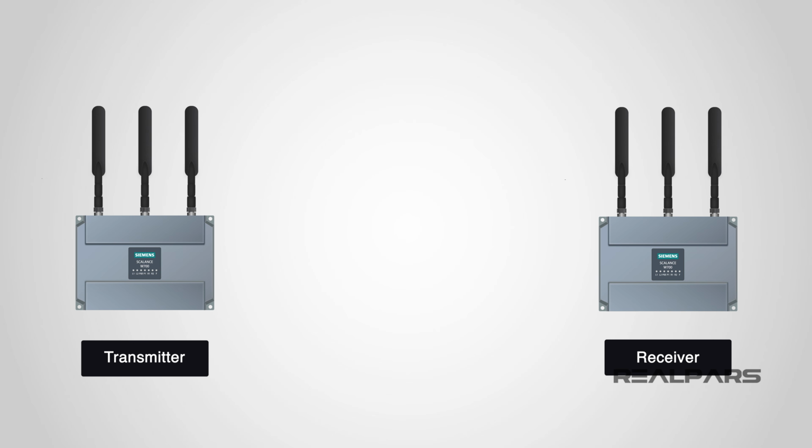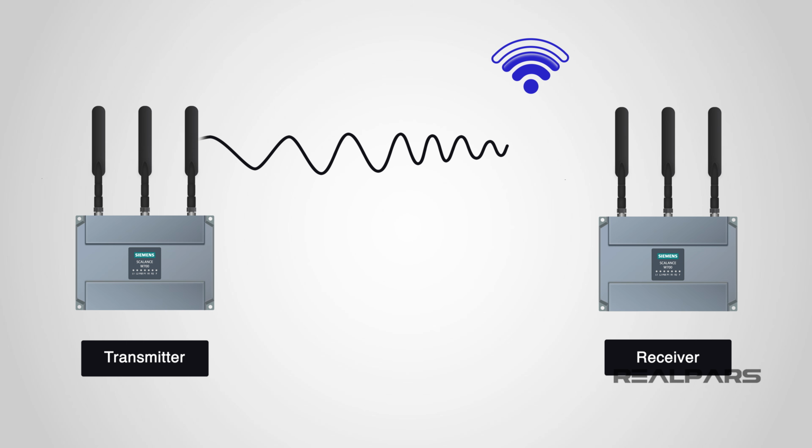Okay, now let's discuss how far a radio wave will travel or propagate, and what are the elements interfering with or attenuating the signal, with a brief introduction to path loss. The transmitter radiates a signal having a specific power based on the size and type of an antenna. The signal, as it travels, begins to weaken or attenuate based on the environment and landscape the signal travels through. The phenomenon of how the electromagnetic wave weakens is known as path loss.